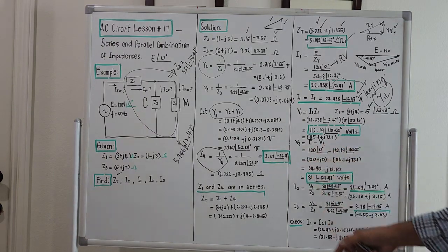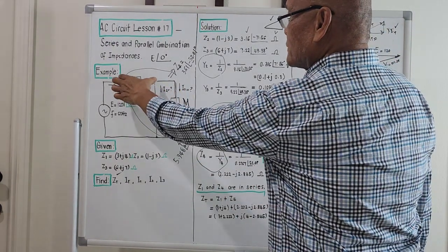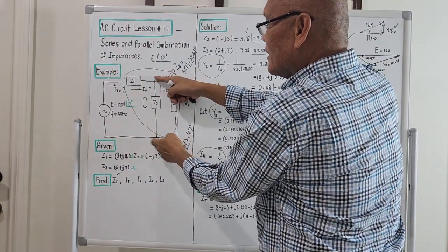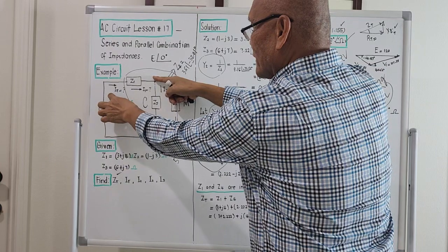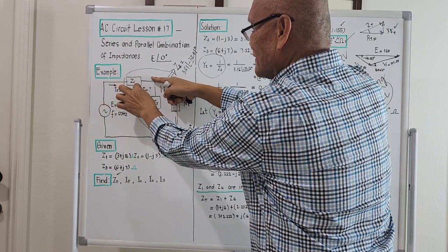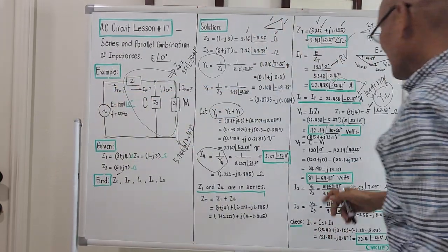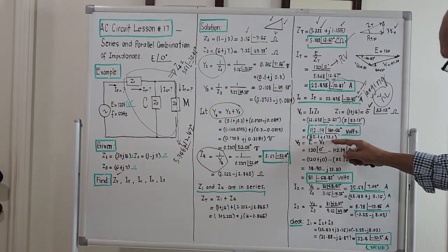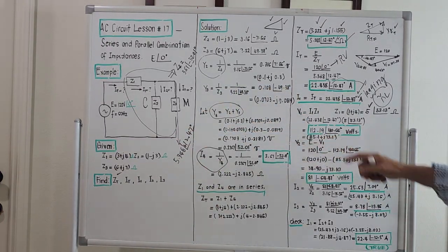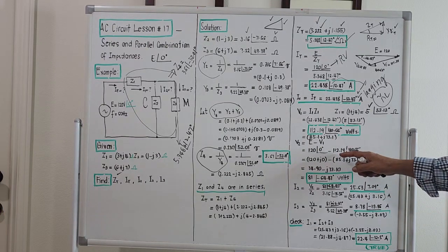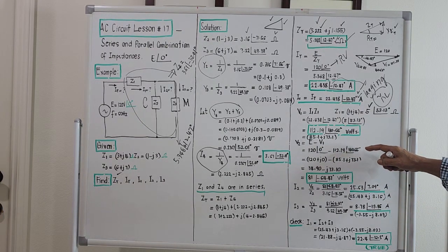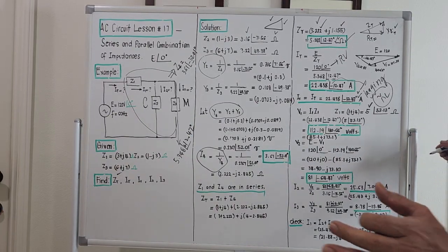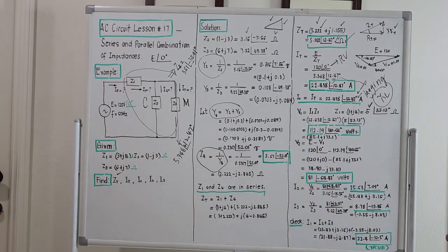So V2, we now know the voltage across this. To get the voltage here, we will get the applied voltage minus the voltage here, right? So I place it here, V2 will be the applied voltage coming from the utility line minus V1: 120 angle 0 degree minus 112.19 angle 40.66 degree volts. You subtract this one vectorially.